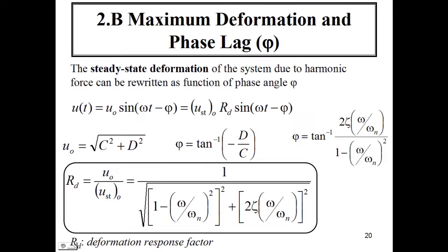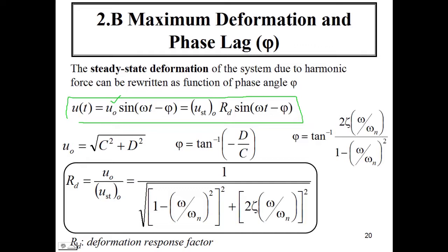Maximum deformation and phase lag phi. The steady state deformation of the system due to harmonic force can be rewritten as a function of phase angle phi, as shown in this equation, where U0 is the amplitude of the steady state deformation, Rd is the deformation response factor, and phi is the phase angle.